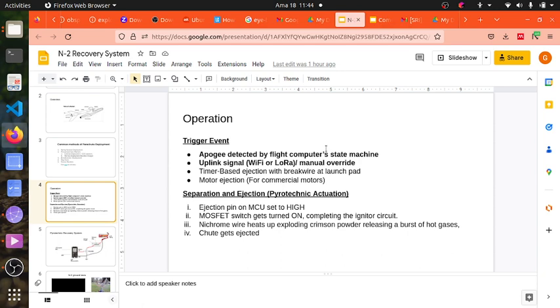So these readings can be monitored, and then you can know, for example, when I get to 500 meter height above the ground level, then I should deploy the parachute. So this is using altimeters to detect the apogee, and then you deploy the parachute.